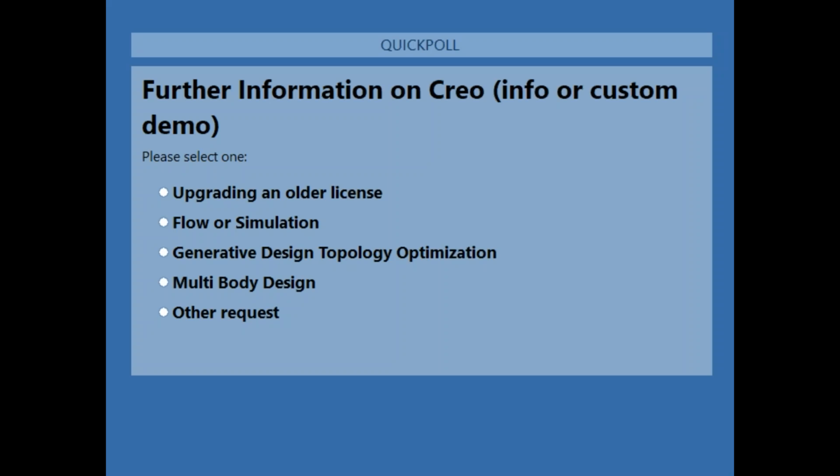The other question is with respect to the boundary conditions and loads. It is common in optimization to have to design for more than one load case, and it does all of them at once. However, you do have the option of going back to the model tree and simply suppressing the ones you're not interested in. So indeed, you can use multiple load cases. It just does whatever is active, it does it at once. And if you want to do a different case with different loads, no biggie to do that.